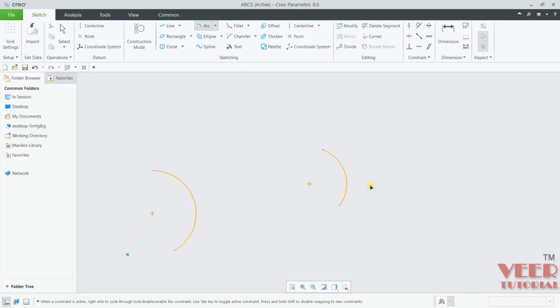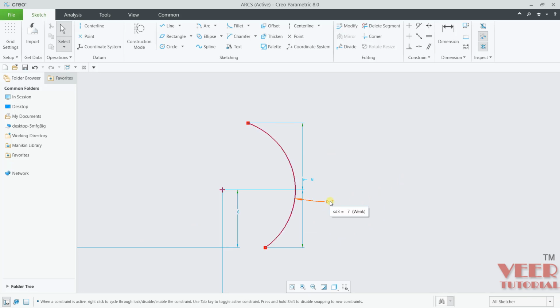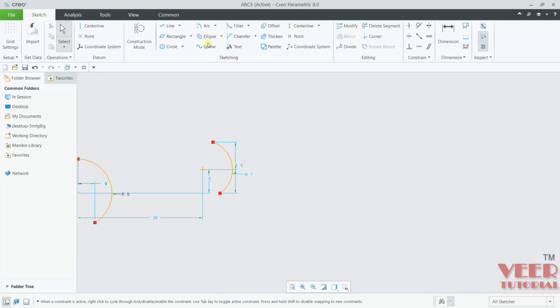For this circle, you can see with these 2 points, the radius of the arc is already defined. So now we cannot change this radius, we can only go through this circle. I will select this point here, press escape. Now you can see the arc. For this arc, once again we can change the value of this radius. Now the next type of arc is 3 tangent.